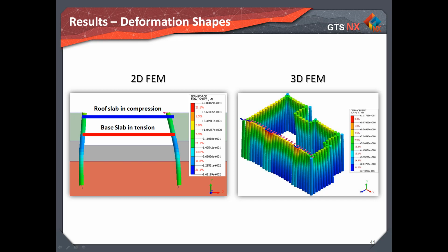Considering the cantilevered wall is already supporting the earth and column rows, that is passive resistance mobilized, once the slabs are connected, we wouldn't expect much of a load before barrier wall is applied, unless relaxation or age analysis is modeled, which is not the case here.